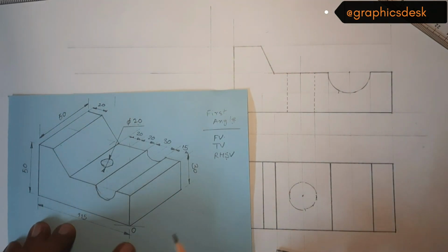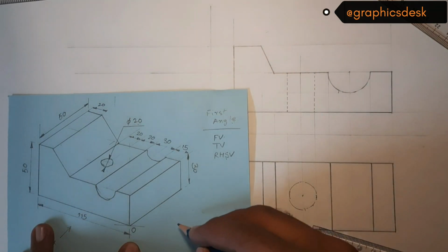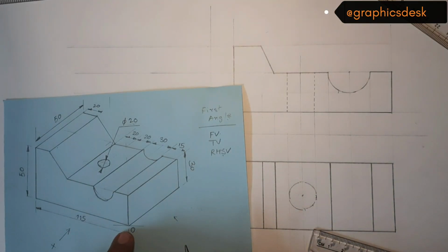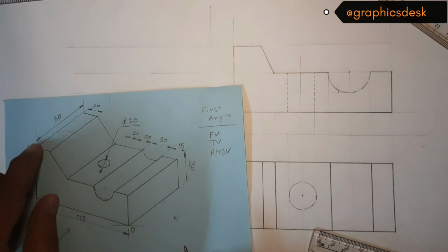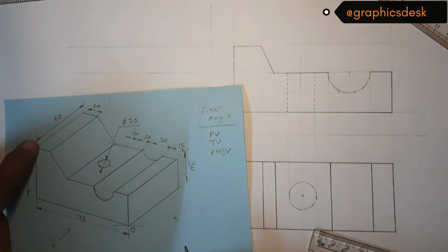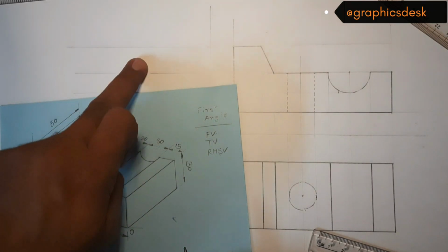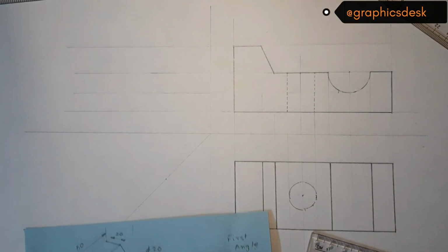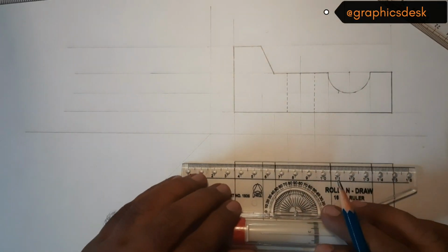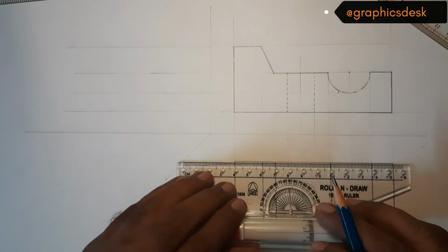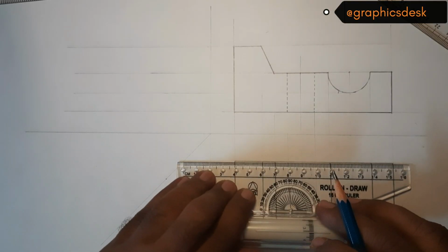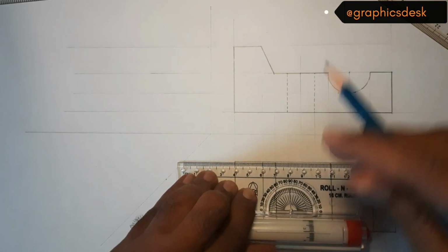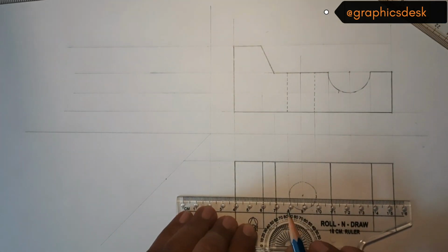Now the geometry on the right hand side view, where the observer is looking in this direction, the maximum boundary of it is 50 mm in width and 50 mm in height. So it will be a square diagram in the right hand side view, and as you carry the projections, it will take its shape. So I'm carrying the projections from the top view now up until this point, the line which we have drawn as XY line.